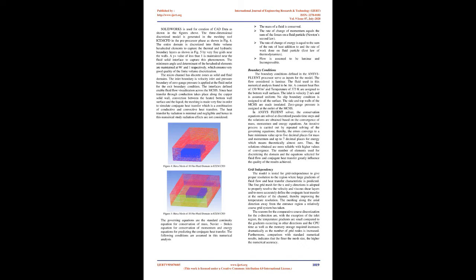In a confined geometry, the small flow rate within microchannels produces laminar, smooth flow, which results in a heat transfer coefficient inversely proportional to the hydraulic diameter. In other words, the narrower the channels in the heat sink, the higher the heat transfer coefficient.